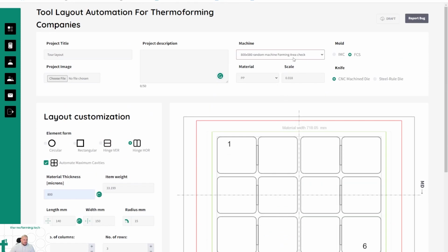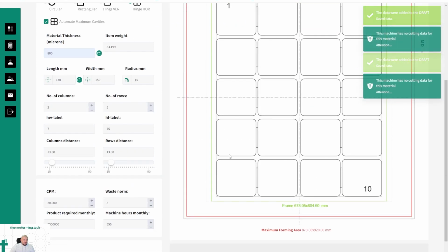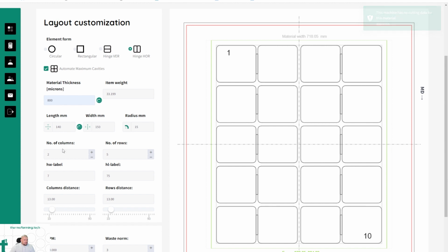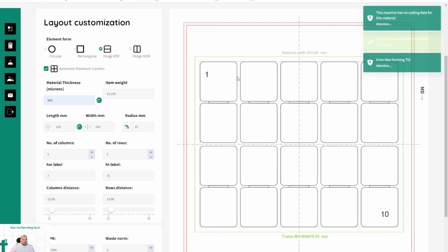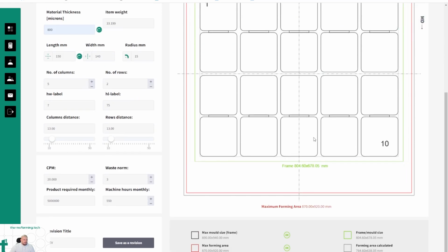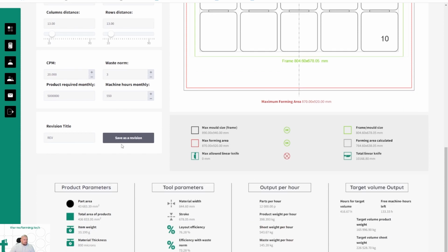For example, let's go to something bigger. Yeah, I know we have GN915, which is huge, and we have Impact TS1000, and we have KMD90 Kiefel. If we go to KMD90, look, we can place 10 cavities, but let's reverse it like this. Let's better place 10 cavities so it's easier to stack the products. So with 10 cavities on the mold, the same speed, as you can see now, 12,000 parts per hour and 400 hours, and we still have 130.